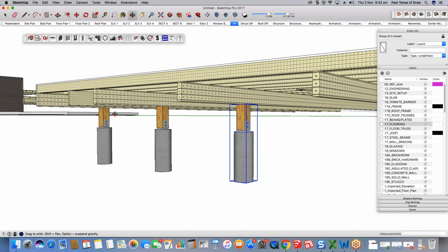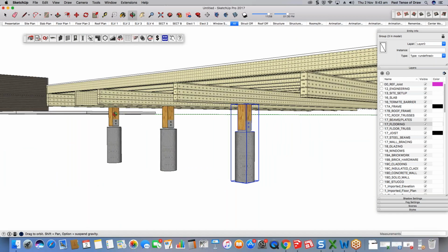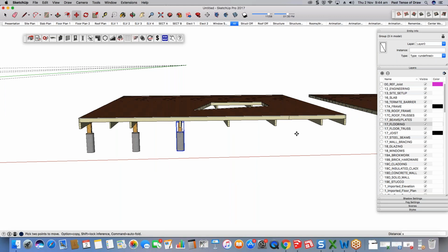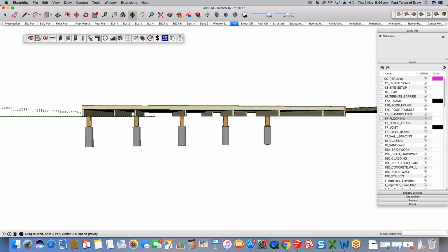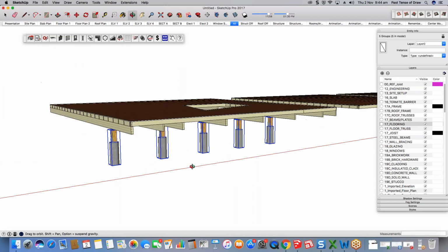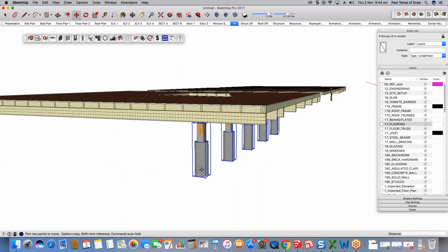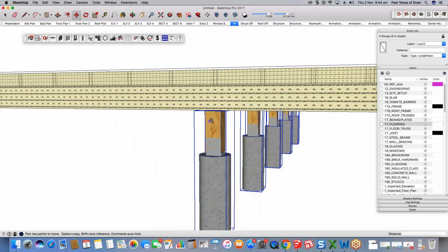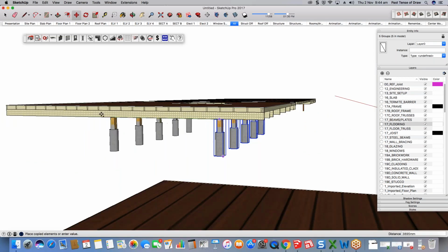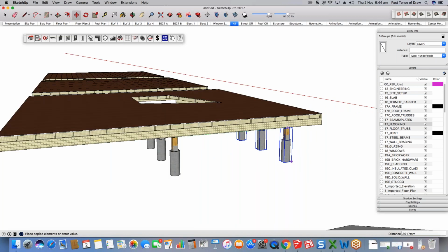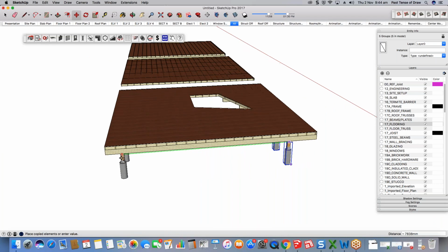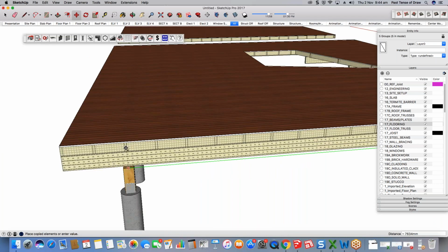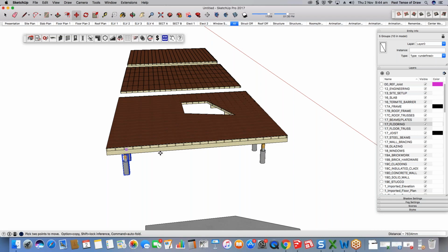Now again, if I knew the spacings were all the same, I could simply type X3, and I can keep on going. And if I know that I've got a certain spacing the other way, I'm simply selecting it, grabbing it from a point, and telling it what the measurement is. Maybe I need 2 in this case, but maybe I need to divide it. So again, this is where we're getting back into the idea of I might know it needs to be there, but now I actually know that I need a second item in there, so divide it by 2.